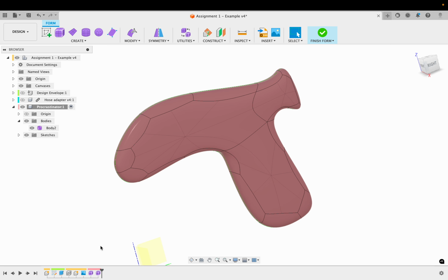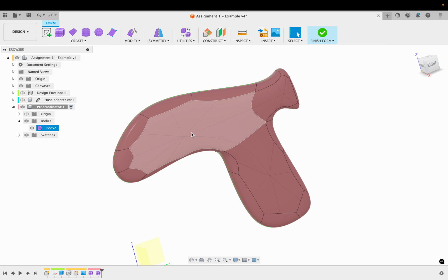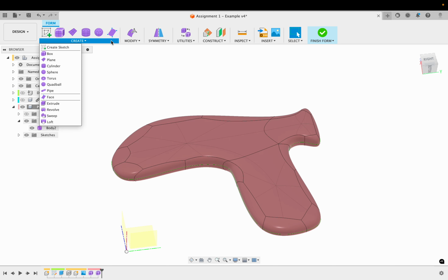Okay. So first of all, thanks to my incomplete freeforming skills, I did the wrong function when I tried to close this thing off. What I did wrong was that I tried to close it off using face, which I could have done. But if I should do it that way, I should segment this into several parts. So I should perhaps make one face for that part, and then one face for the middle, and one for the back. That would be one strategy.